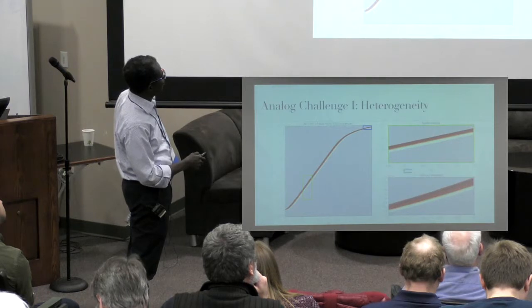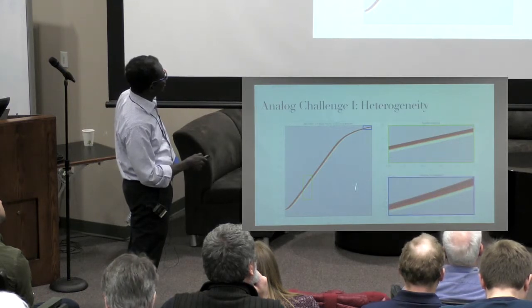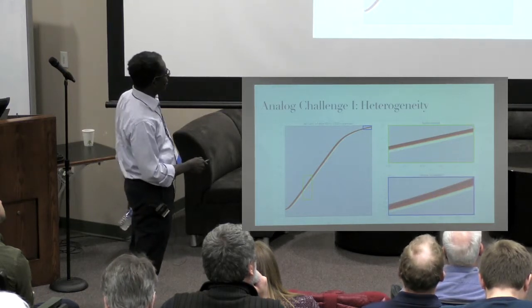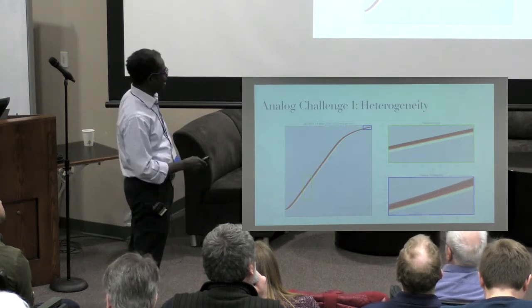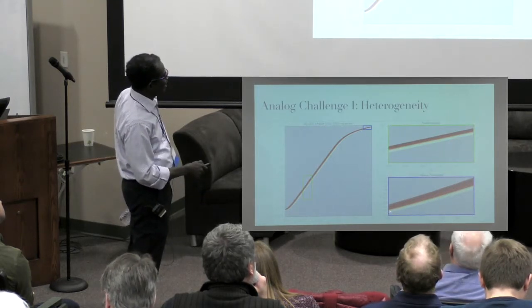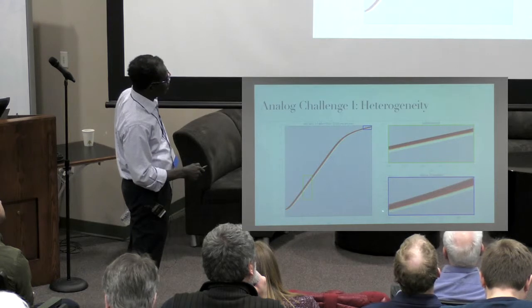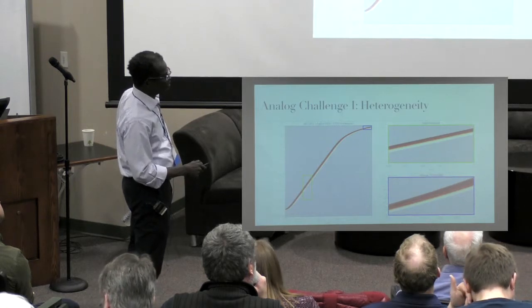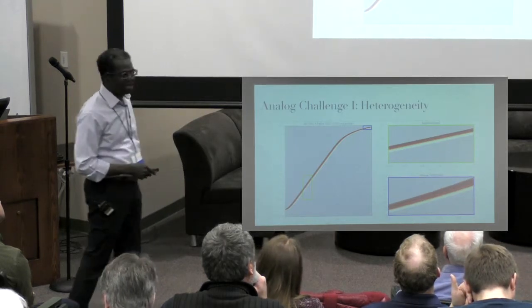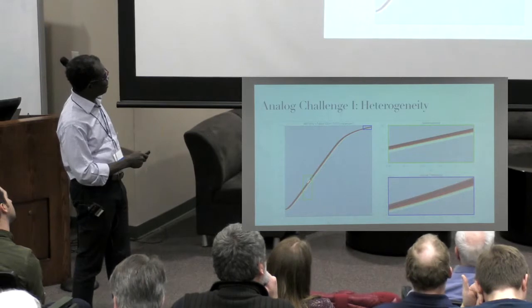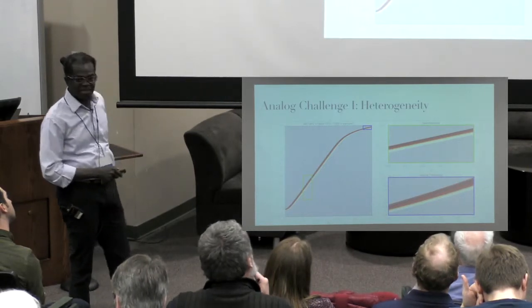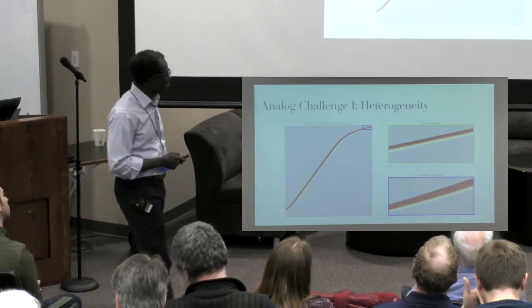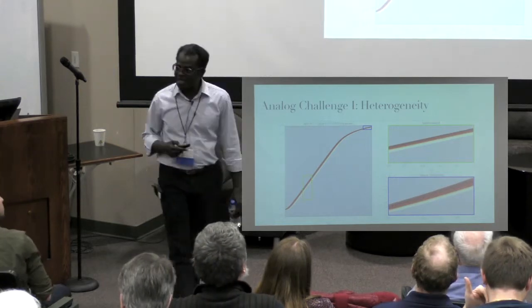Most people build analog stuff up here where they are passing a lot more current. Your iPhone would just last for less than an hour, maybe 10 minutes, if all the transistors were operating up here. And here you only have maybe from 3.5 to 4.5 or something, 25% variation in the current for the same voltage. So we are down here where we are exponentially sensitive to what I call threshold voltage mismatch. And it's about a decade, so that's huge variability.